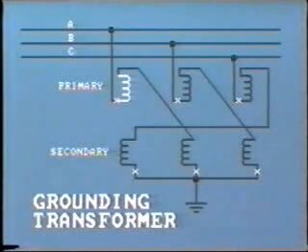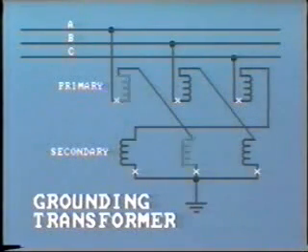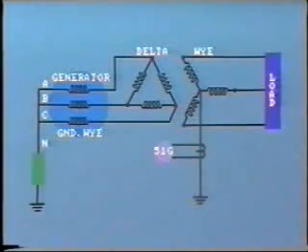You can see that the A primary winding is connected in series with B secondary and so on. This allows only ground fault current to pass through. We have pointed out that in utility practice, the equipment is usually solidly grounded at voltages above 40 kV. Now, at lower voltages, sometimes equipment is grounded through an impedance to limit fault current. An example is the generator neutral.